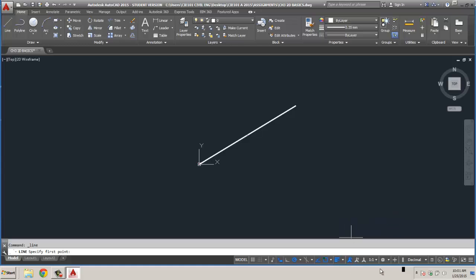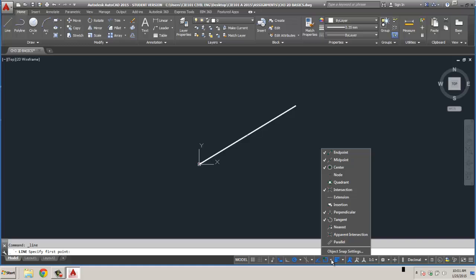If we look at our snap points, we want to look at this tool right down here at the bottom, snap cursor to 2D reference point. It's on. F3 is actually the toggle. Your function key F3 will toggle it on and off. So that's your on-off switch for object snaps, or O snaps. If we drop this down, we can see that currently we have endpoints, midpoints, center points, intersections, perpendicular, tangent, and the rest of these are not turned on right now. And this is probably good for what we need.